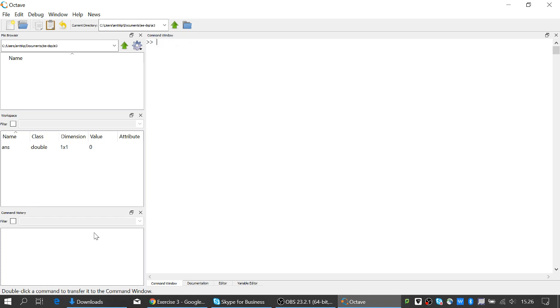Okay, but anyways, so let's think of a system. I will start it from a different point of view. You will actually have this flow chart to work with, but basically where I'm starting is from zero pole plots. Just to show how to generate these system coefficients from zeros and poles instead of from a picture. Just to show another view. Okay, zero pole plot.